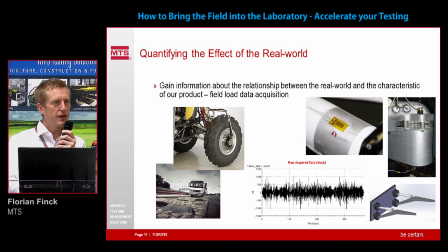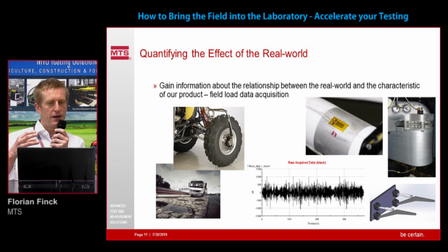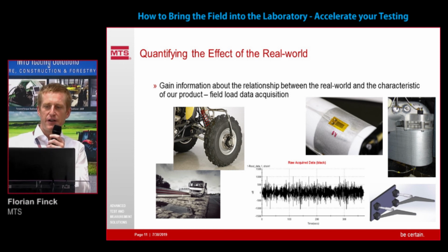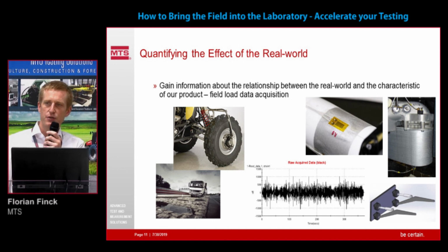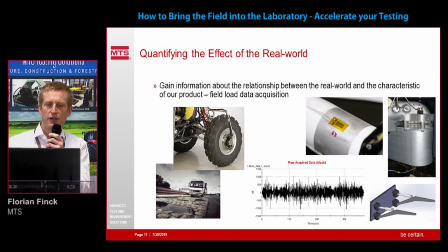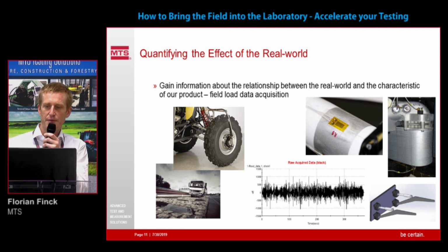You can take a wheel force transducer, as Stefano just has shown, to acquire forces and moments directly on the wheel hubs. In some areas it's very helpful to add strain gauges, so you can go to your structure and see what the response of your structure is, not only what the input signals into the wheel hubs are.